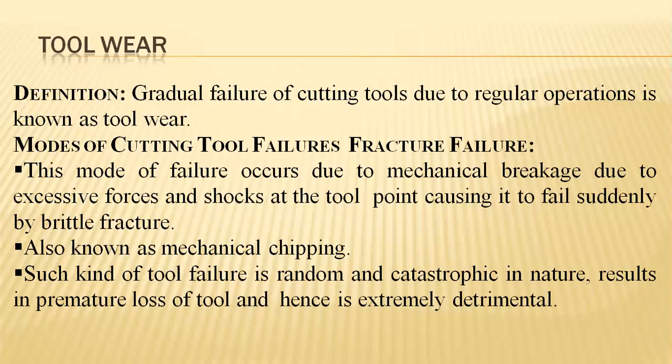Hence, what are the different modes of cutting tool failures or fracture failures that will occur? The mode of failure occurs due to mechanical breakage because of the heavy forces acting at the tool point, which leads to sudden failure because of brittle fracture.